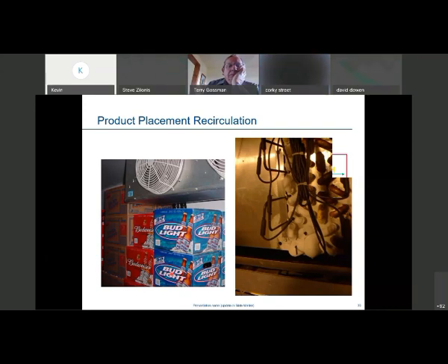This is not acceptable, although it happens all the time, and that's how we sell compressors. But stacking things up underneath there to where you have no return air coming back through here. When you slow down that return air, you get a freeze-up problem like this. You'll see ice banding and some real problems.